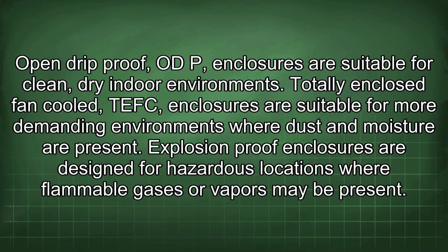Open drip-proof (ODP) enclosures are suitable for clean, dry indoor environments. Totally enclosed fan-cooled (TEFC) enclosures are suitable for more demanding environments where dust and moisture are present. Explosion-proof enclosures are designed for hazardous locations where flammable gases or vapors may be present.